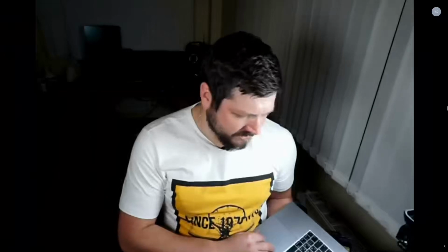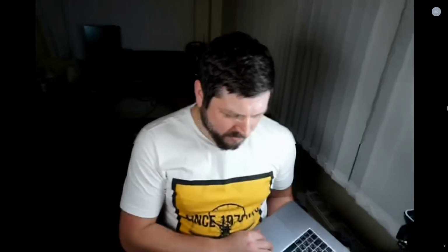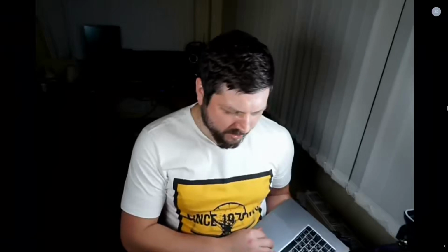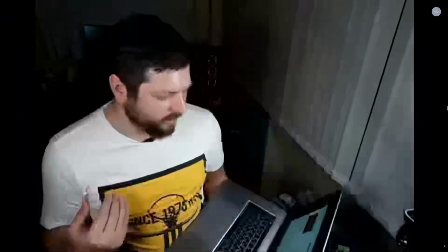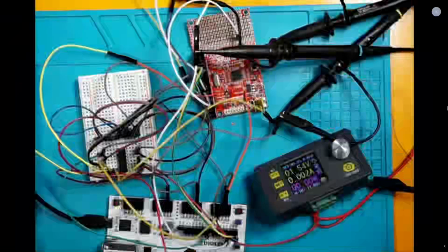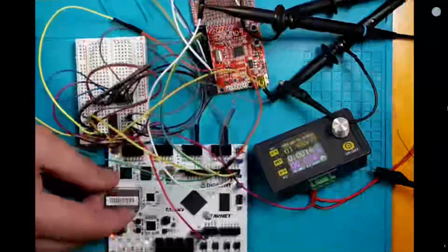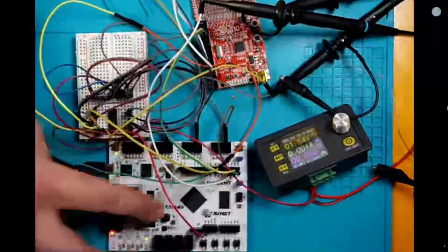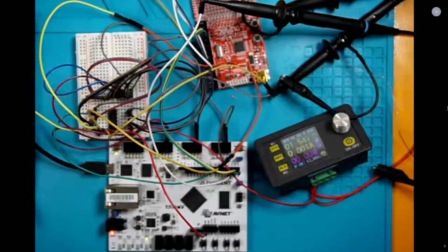And then finally, there was another question. You have the FPGA connect to the reset pin to the power supply via the multiplexer. With a Python script, you interface with the FPGA over UART and vary the delay of the width of the glitch. So yes, all parts of that statement were correct. What's actually happening is I'm implementing on the actual FPGA a state machine, which is parsing its command, which sets the delay and the width.